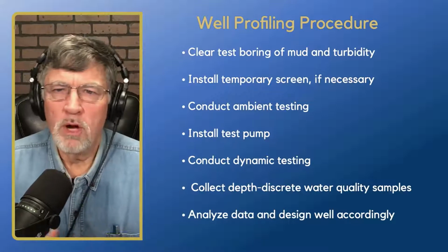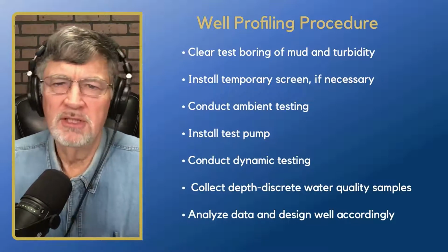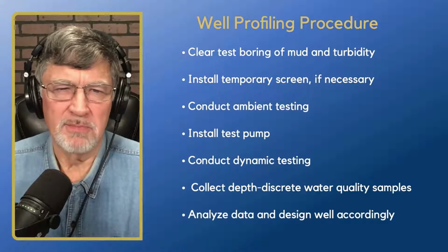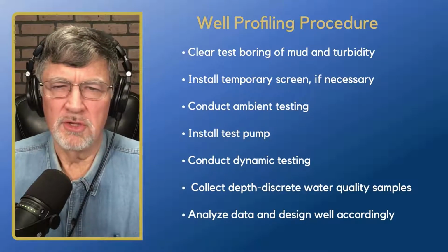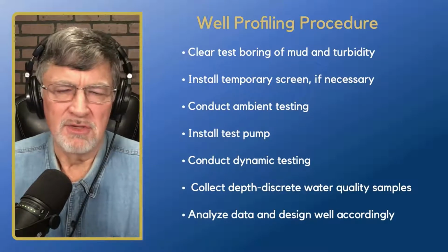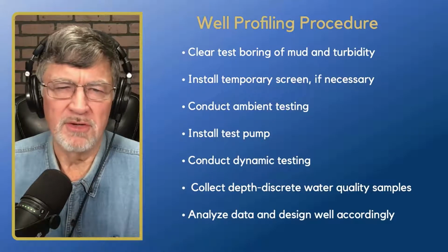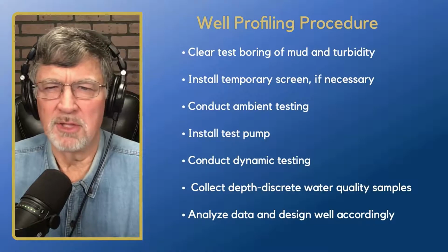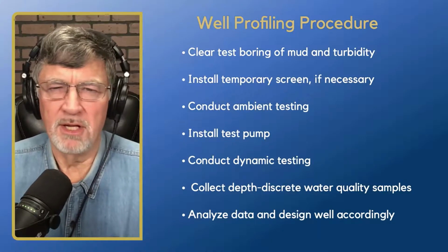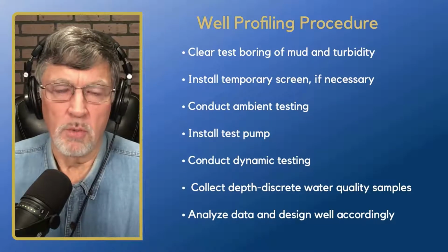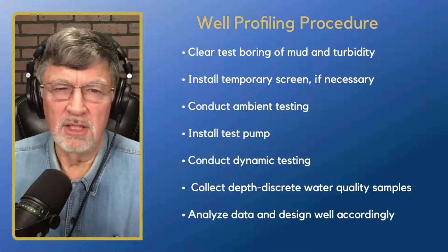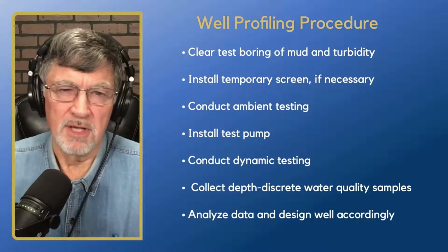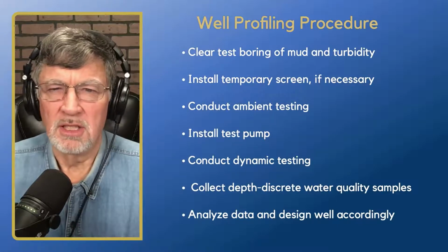Okay, so our well profiling procedure: after we drill our test boring, we're usually going to thin the mud down somewhat so we can go in and do our geophysical testing. But you're going to need to thin things out and clear the test boring of mud and turbidity before you can do your well profiling with any of these meters. And probably the dye traces as well.